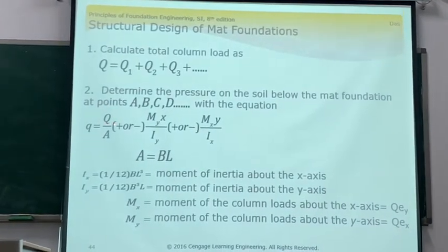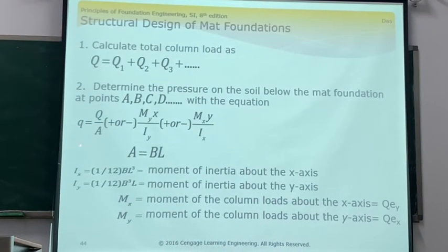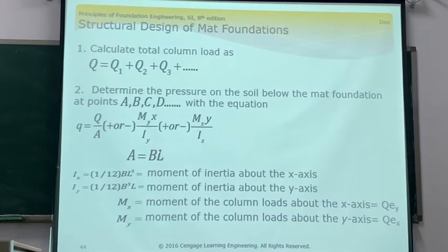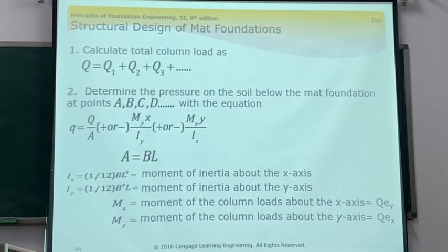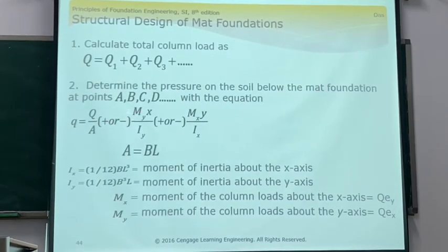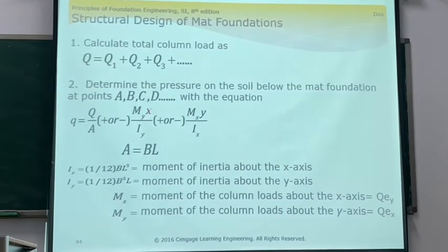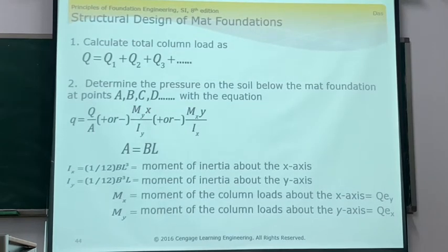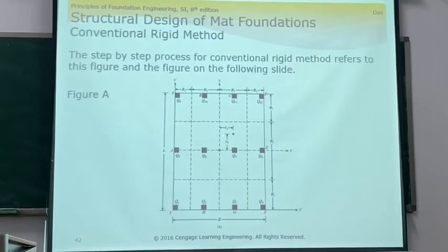So use Q by A, which is B times L, plus or minus MY times X over IY. And we can see this in the figure.